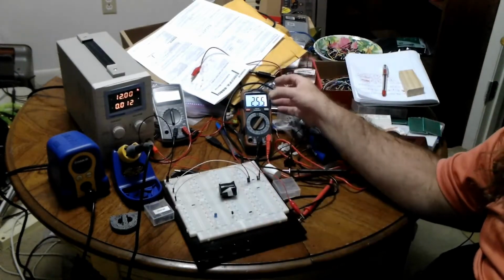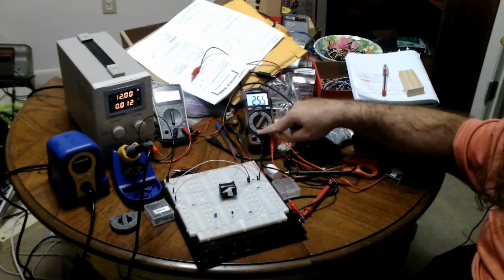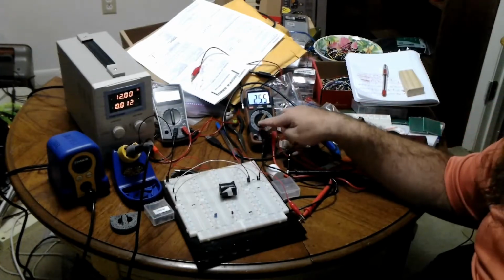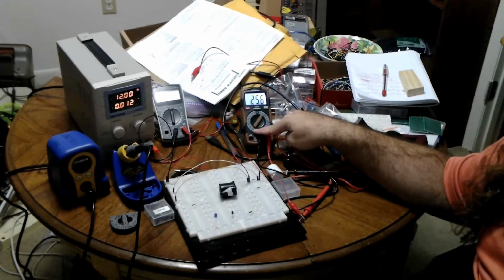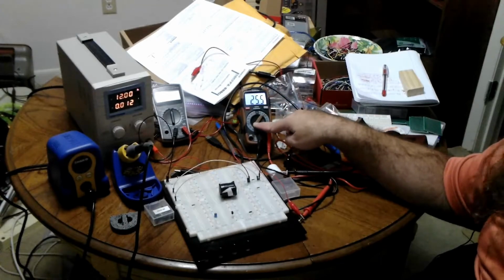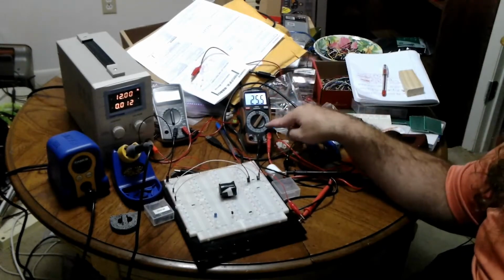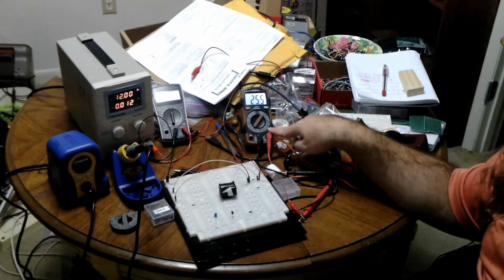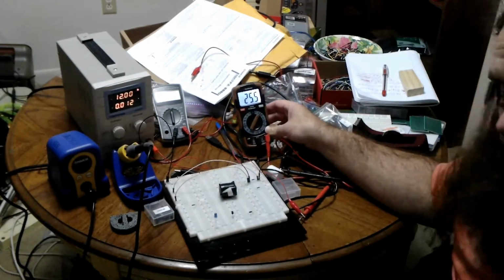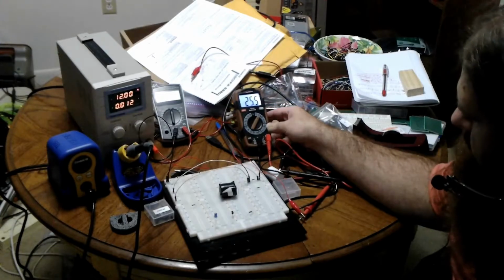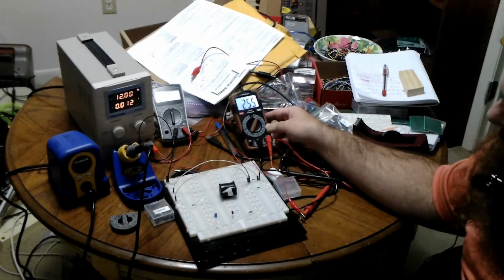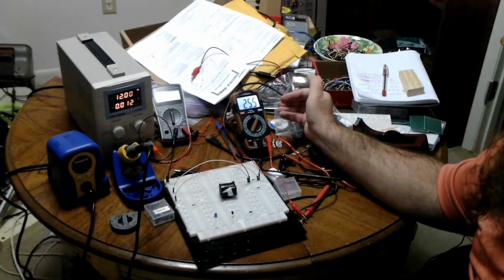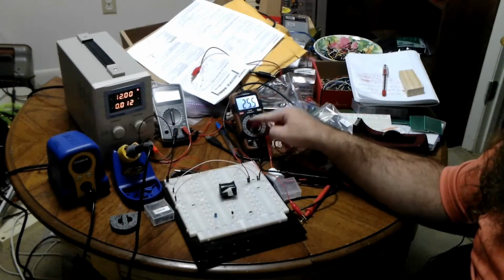The first clue is to think about this meter. It's got resistance settings. That works by applying a DC voltage. The meter applies the voltage and measures the current. It's got the diode test mode and continuity mode, which is again applying a DC voltage. It's got a battery checker. Those are DC devices. It's got a high amperage, but that's DC. It's got low amperages, and again, all the amperages are DC, and then all the DC voltages.